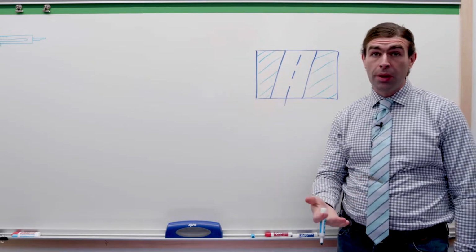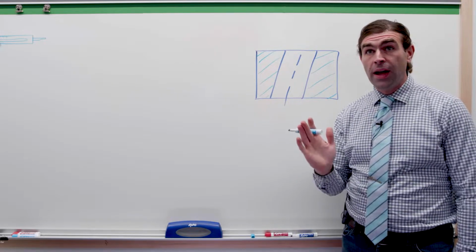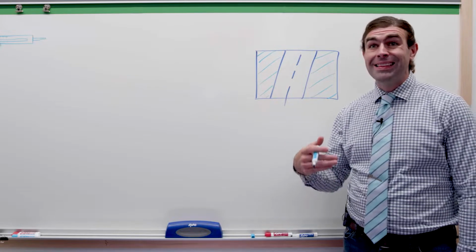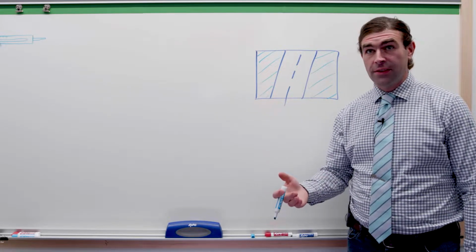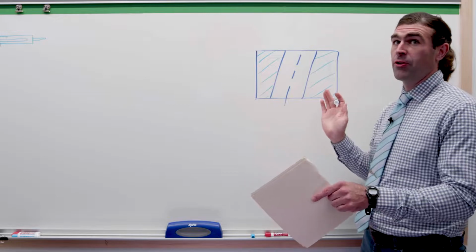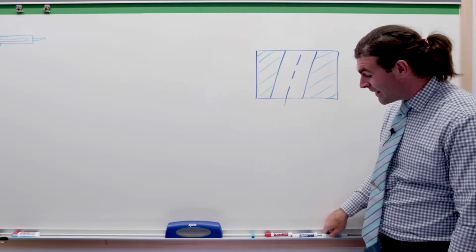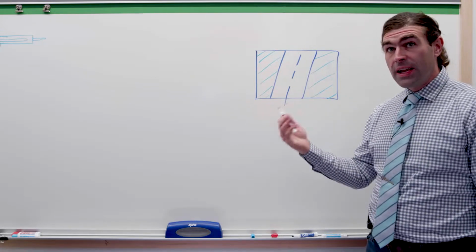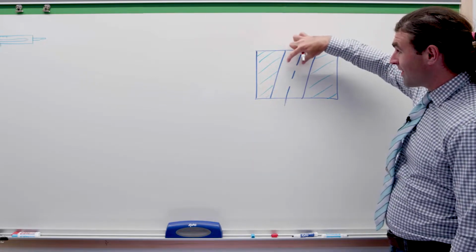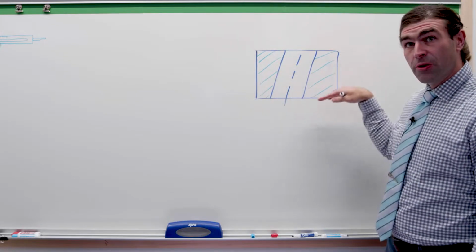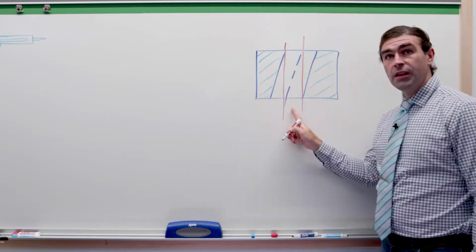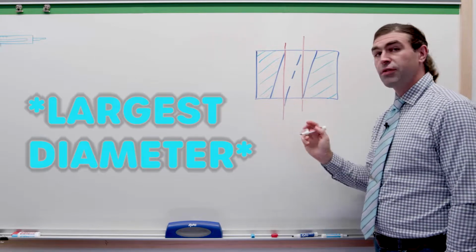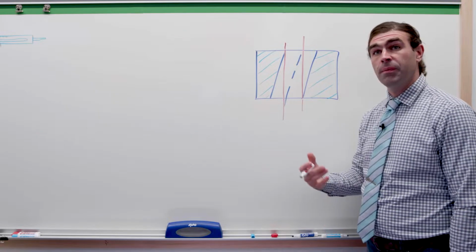not. Whenever you apply a position tolerance, you're implying that there is tolerance. The hole doesn't have to be perfectly straight. The size tolerance also adds to this because now the hole can be larger or smaller. So in this case, without knowing any tolerances or anything, we could say our inner boundary, so the smallest thing that could fit in here and be perpendicular to one of these faces, is right here, right? So from this point to this point, this would be the smallest diameter that could fit through there.